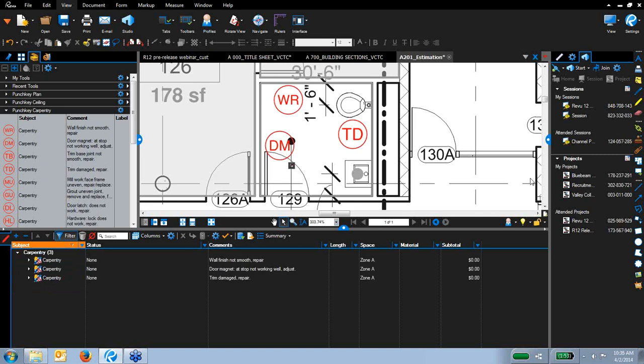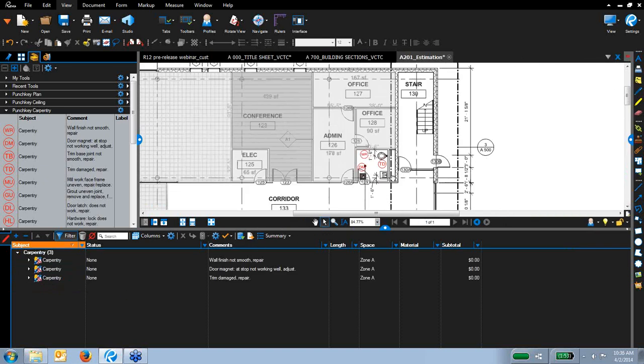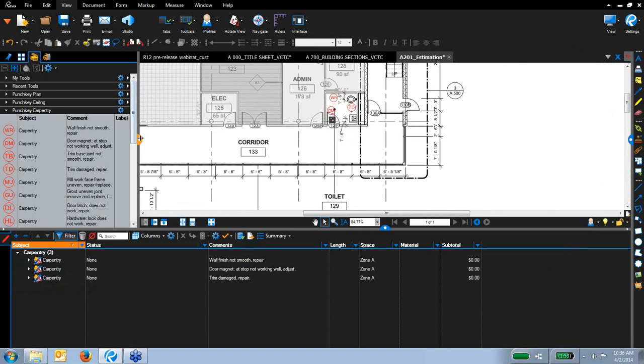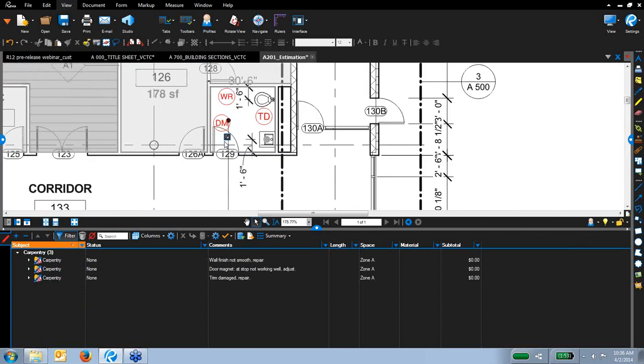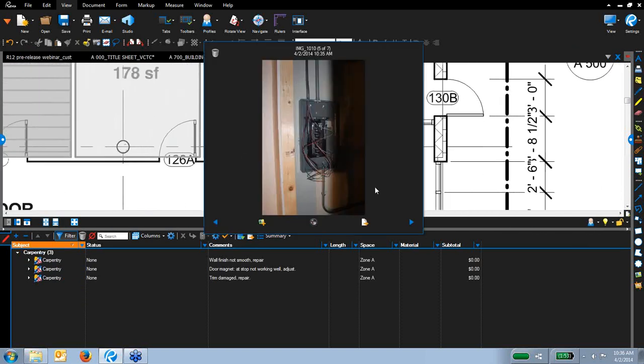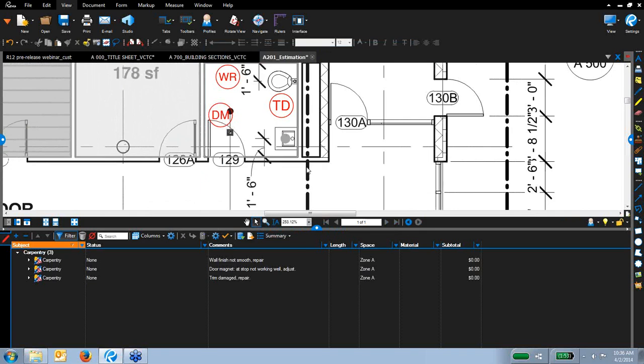Now, something to note is that Capture is actually outside of the PDF ISO standard. So this function, where they can click on this button and see that photo gallery, only works if they're currently using a Bluebeam software: Bluebeam Revu, Revu iPad, or Bluebeam View. If they're using another PDF software, they're not going to see this little camera pop up. They're not going to see those pictures.